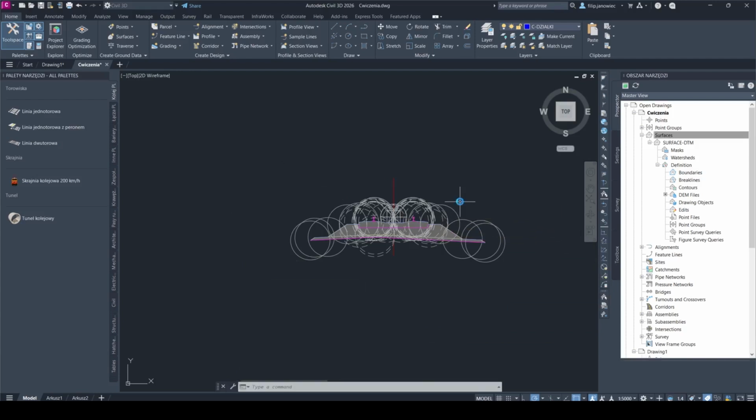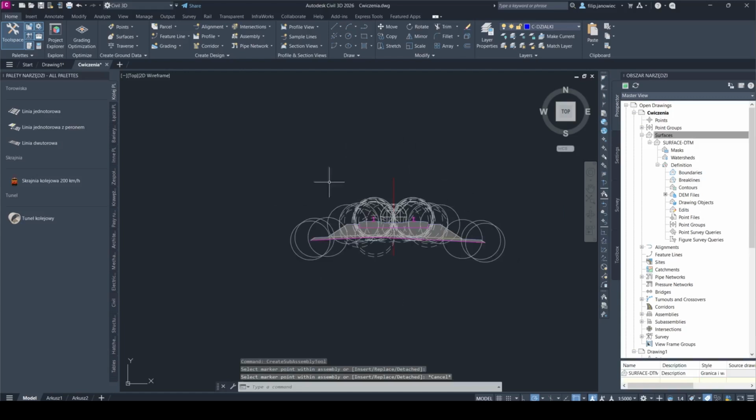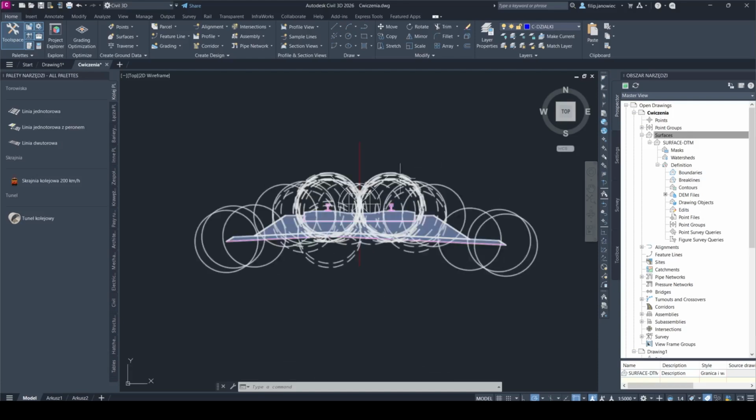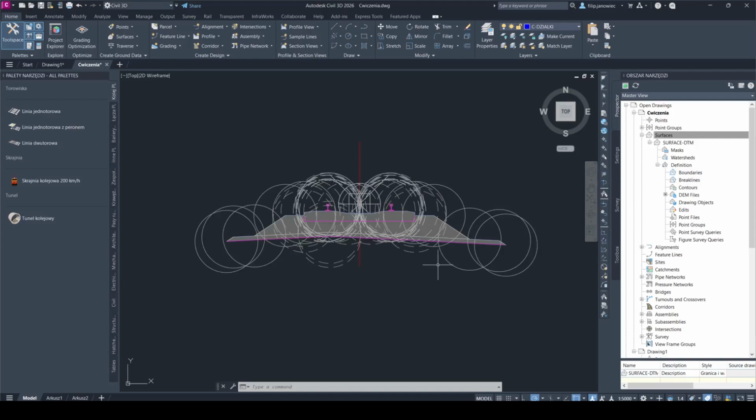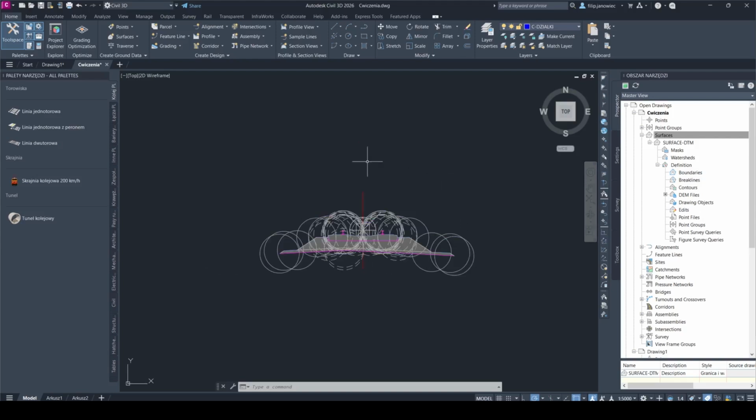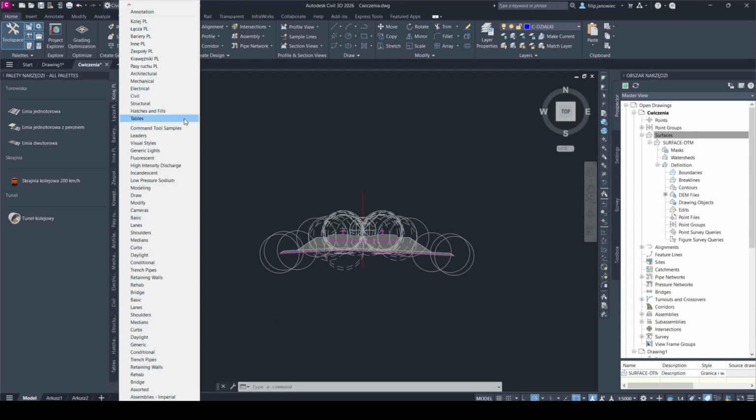As you may see, it looks quite better than before, but there is an option to adjust this and the previous one. Okay, we don't bother about the circles. The circles must be shown, but what we must also add are the slopes for the cuttings and the embankments. So we must look for the other sub-assemblies for our assembly, and I choose the basic.